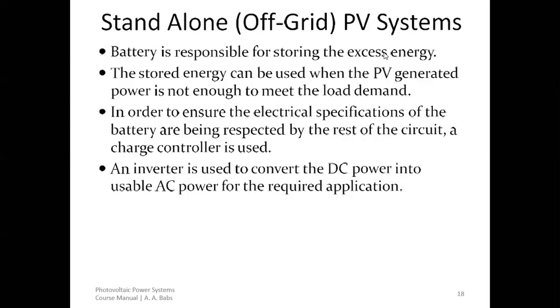This means that when the PV array has converted the energy of the sun, the solar energy, to electrical energy, first, a portion of it will be stored in the battery, and second, a portion of it will be moved to the standalone inverter to convert it to AC. And then a portion of it would also be used directly. So that means 3 places, okay? The energy from the PV array will go to 3 places.